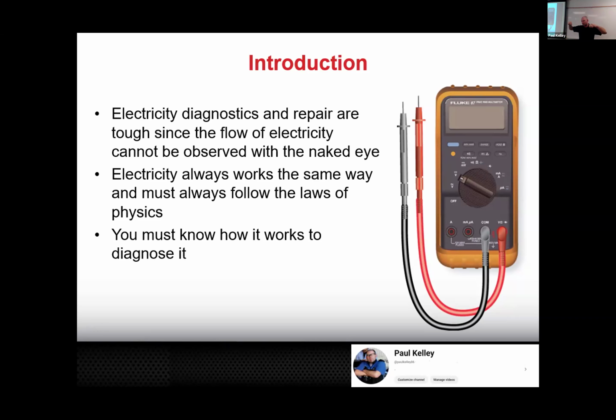But if you were to measure it, and you were to see you had an excessive voltage drop or excessive resistance in that connector, you know exactly which wire, exactly what terminal, you know exactly what's wrong. You've taken a measurement, right? So when possible, we want to be 100% sure. We want to be able to prove what the defect is with an actual measurement, okay? So that's how I want you guys to think about it.